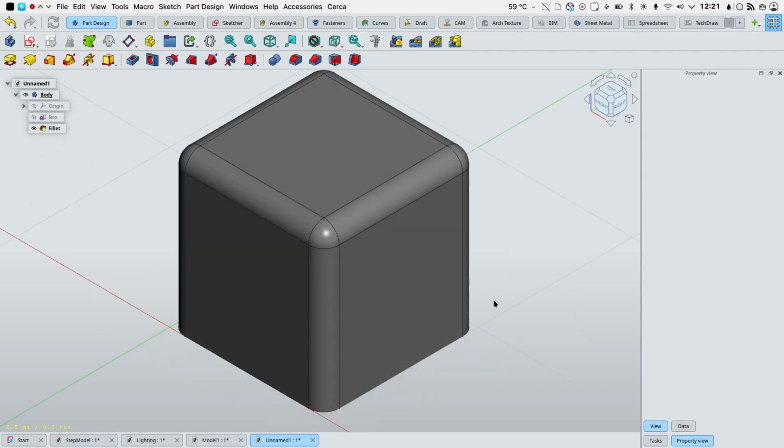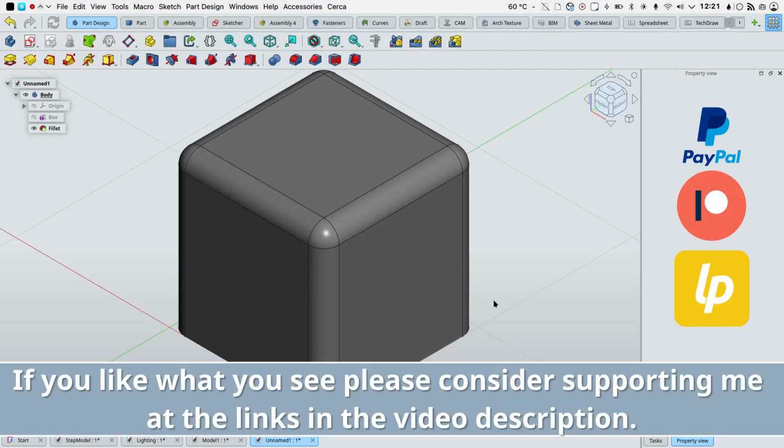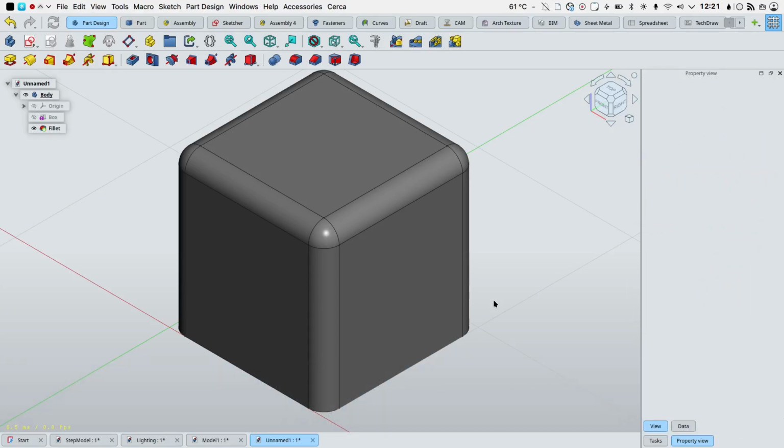By default, FreeCAD's 3D view is quite plain. It has only one light source, and in the latest revisions of the software, this can be configured in the Preferences dialog. We will use this ability to configure the source of light in conjunction with an add-on called Arc Textures to achieve what is called 3-point studio lighting.